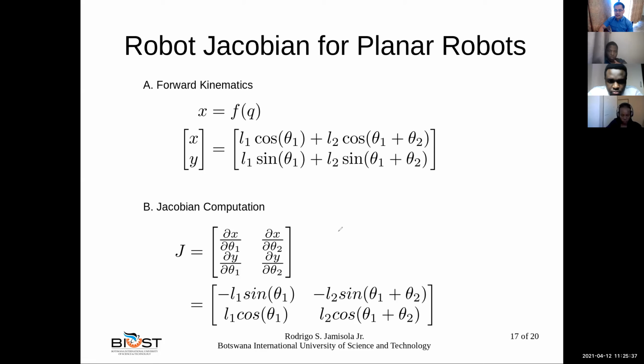Once we understand the planar robot, that's how we start to deal with much higher dimensional robots, from 3 up to 6 joints, where we are going to use transformation matrices, rotation and translation. In this case here, we're not using matrices, we are just using analytical computation.